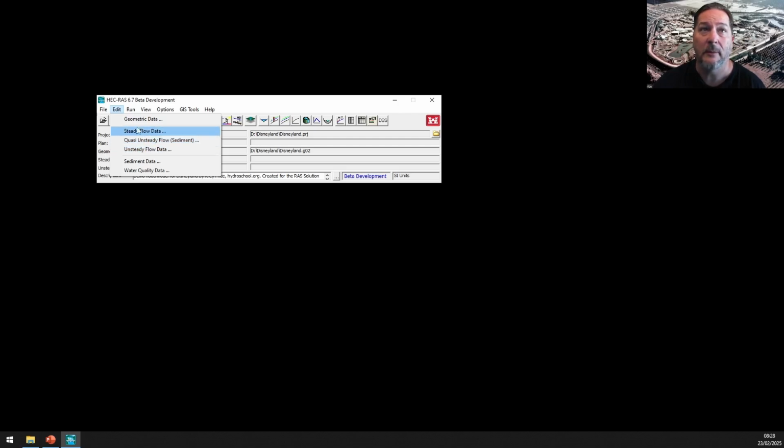So let's talk briefly about steady versus unsteady flow. For a 1D model, you'd actually have a choice between the flat water surface here, it's a Q, that's the discharge, versus this one here, which is a Q as a function of time. That's the T in parentheses there, going up and down over this hill. For a 2D model, you wouldn't actually have a choice to use this one here, the steady flow. You would only be able to use unsteady.